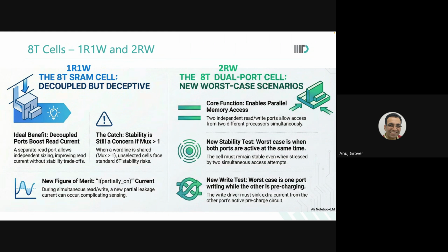But it is also far more complex to design. And therefore, keeping the design parameters in mind when we build it, the dual port memory is slower than the single port memory. So you wanted to avoid stall states and have overall better throughput. Now, since your memory is slower, throughput anyway goes for a toss.